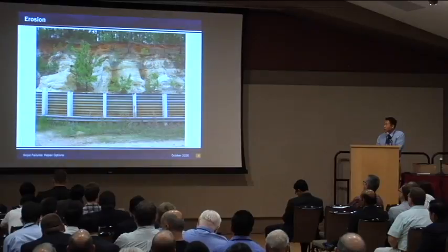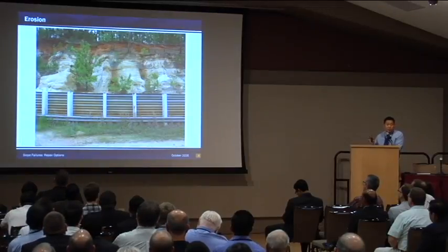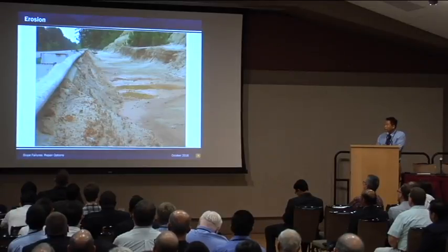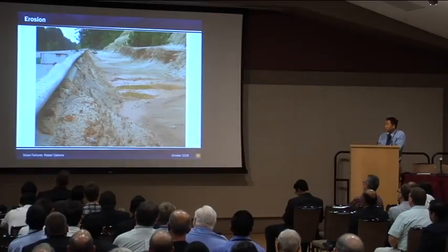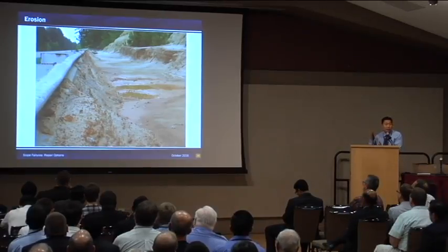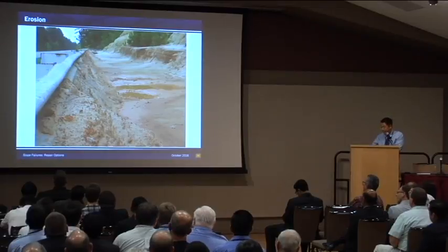This is the typical erosion failure, or erosion issue, in sand or silty material. The surface water can make pretty large erosion issues. So the best way is to properly drain your water, divert it, or protect your surface.